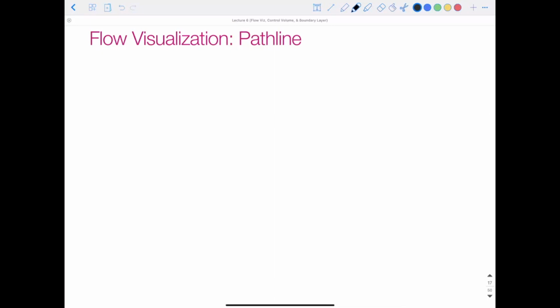So now what is a path line? A path line is a little bit simpler, but it's if we were to just track a particle's path through time, the line that it would trace out for one individual particle would be called the path line. So if we had our particle, it's sitting here, and that's at time t0. And then after some amount of time, it's moved over here, and it's followed this path.